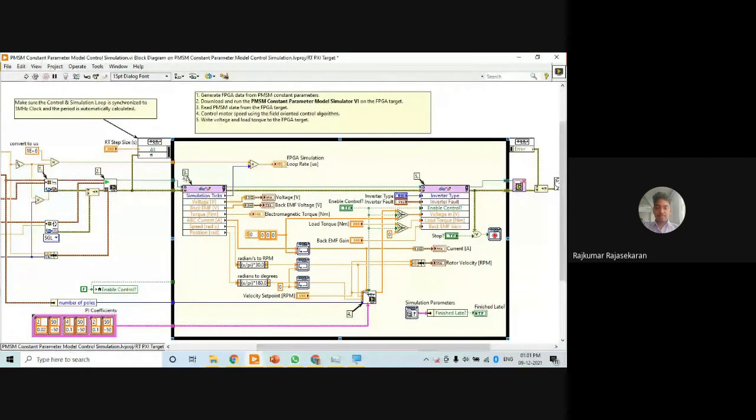And here what happens is this will get data as feedback from the hardware FPGA. It's used to simulate the measurements of voltage and current. This is used to simulate the effect of an ECU. What will the ECU do? It will take the current measurements from the motor, calculate certain parameters to make a decision on what to do next. So it will make the measurements and calculate the FOC. If you see, it's given as an input to field oriented control.